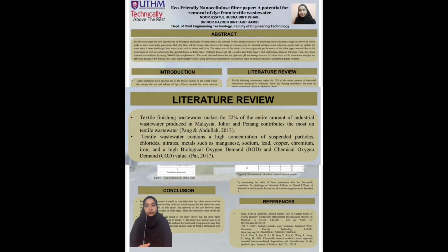In reducing the amount of dye effluent in wastewater, there are several methods that can be applied. According to Al-Tohami in 2022, membrane filtration is one of the most advanced physical technologies utilized to cleanse the dye contained in wastewater. Not only that, a study has been conducted by Chan et al. in 2015 involving CNF filter paper obtained from kenaf core, where the maximum filtration capacity was found to be 122.2 milligram per gram at pH 9.